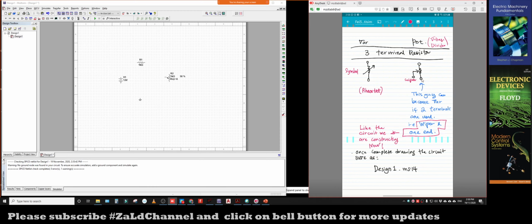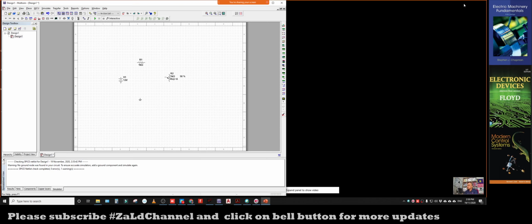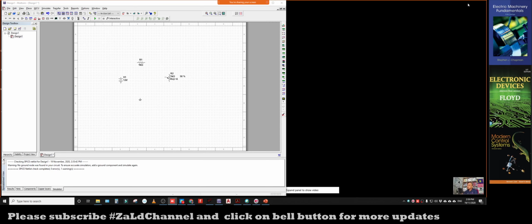Let's say this is the 1 kilo ohm terminal of this potentiometer, then we can connect this 1 kilo ohm terminal and also the wiper terminal, similar to this figure, where I connect the wiper and also the other end of the potentiometer. So basically we can use this potentiometer as a variable resistor. Okay, and the other name for variable resistor is rheostat, right? The potentiometer is also known as a voltage divider component. This is a special component that is used in a voltage divider. We call it a potentiometer.